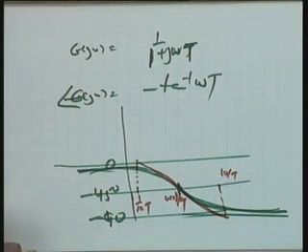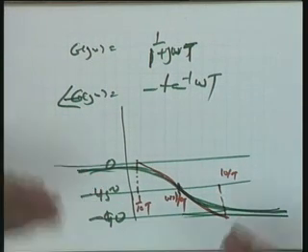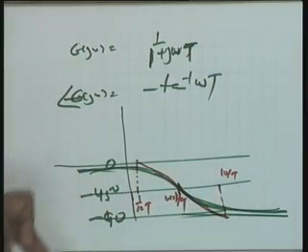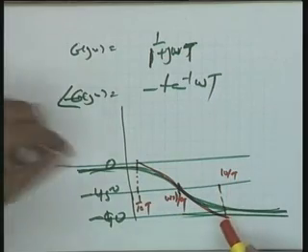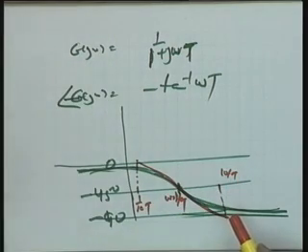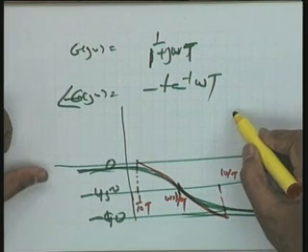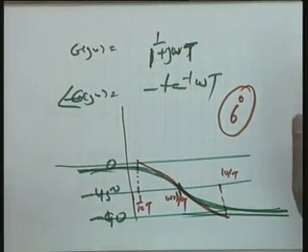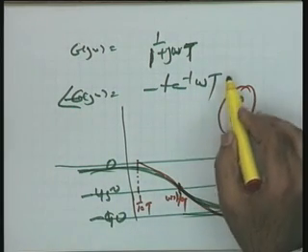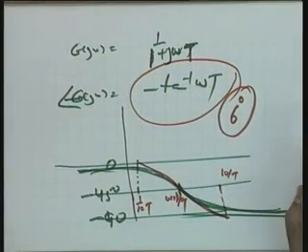So if you are getting a factor of a double pole, in that case it will become 0, minus 90, minus 180 degrees. This will be a straight line passing through the minus 90 degrees line at omega equal to 1 over t. So 1 decade below, 1 decade above, join these 2 points; it is a reasonably correct approximation. But this approximation can give you an error to the tune of 6 degrees, and 6 degrees error in phase margin calculations is an appreciable error. Fortunately, the calculation of minus tangent inverse omega t is not that clumsy.